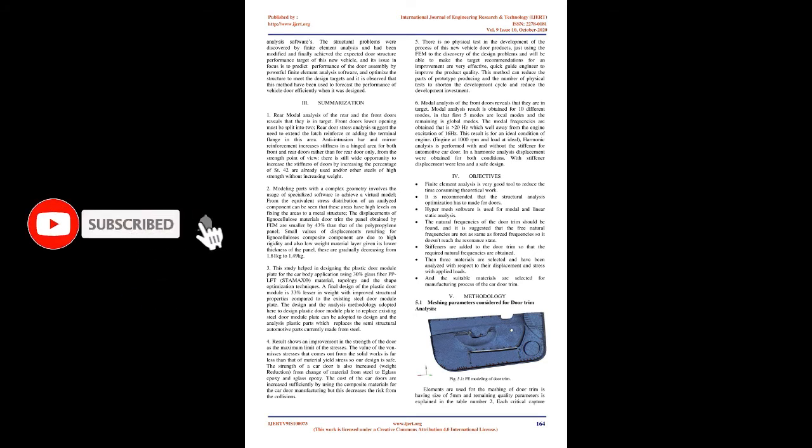Signed von Mises stress. Von Mises and maximum shear stress values are always positive. If those values are used for fatigue calculations, then the stress range would be reduced to half, resulting in higher fatigue life. The remedy is to find the sign of the absolute principal stress at the point at a given time instance and assign it to the corresponding value of von Mises or maximum shear stress. Say absolute max principal stress is minus 300 N/mm2 at 2 seconds and the corresponding von Mises stress at 2 seconds is 315 N/mm2, then the signed von Mises stress would be minus 315 N/mm2.